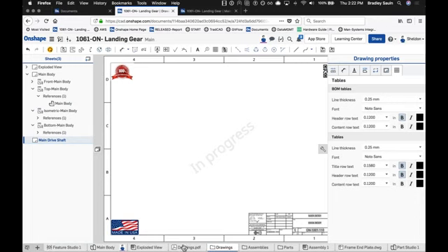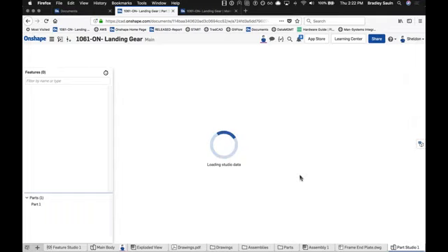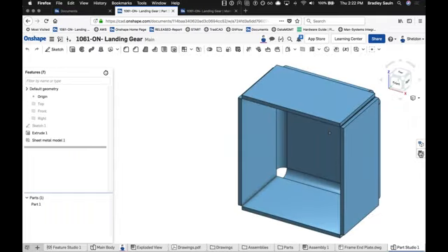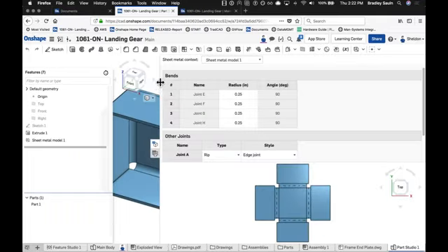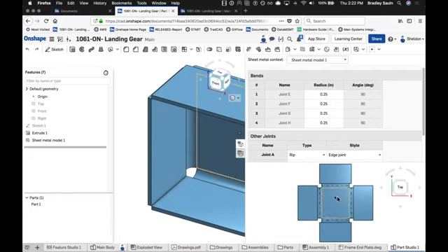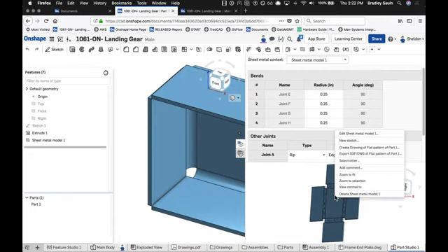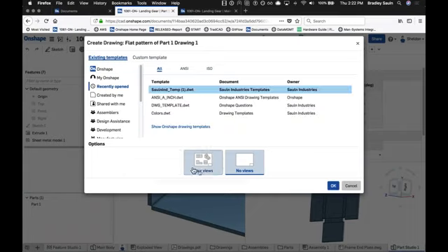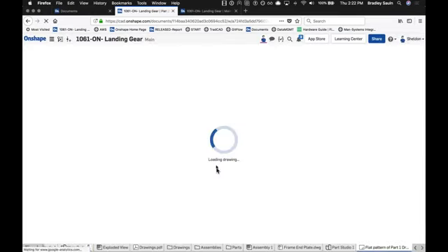We are working with pieces of sheet metal and doing things like grabbing drawings of the flat pattern. So we'll see here again, just that interface on the right, we can see our flat pattern. I can choose to right click on it and then create a drawing of the flat pattern of this component. I'll do no views, just insert it in. Get a nice scale to it.